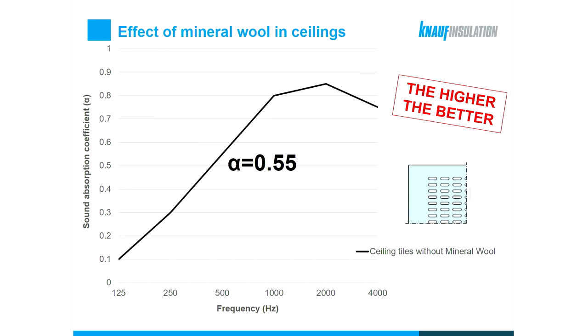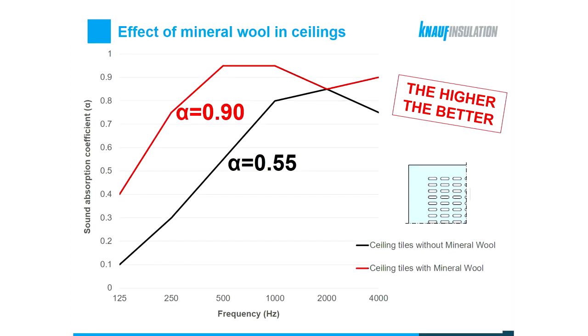In this case, we can say that because of the perforations, some of the sound is trapped in the ceiling cavity, and actually that's why the perforated ceiling provides some sound absorption by itself, unlike the standard gypsum ceiling, which would have a negligible sound absorption. So a standard gypsum ceiling would have most likely an alpha value close to 0.